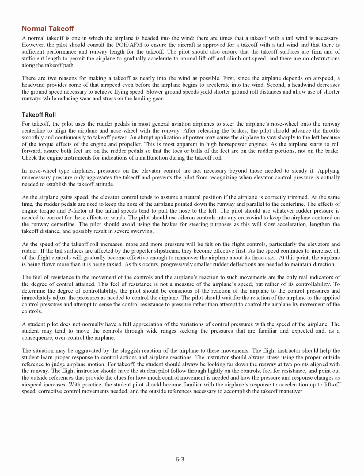In nose-wheel type airplanes, pressures on the elevator control are not necessary beyond those needed to steady it. Applying unnecessary pressure only aggravates the takeoff and prevents the pilot from recognizing when elevator control pressure is actually needed to establish the takeoff attitude. As the airplane gains speed, the elevator control tends to assume a neutral position if the airplane is correctly trimmed.